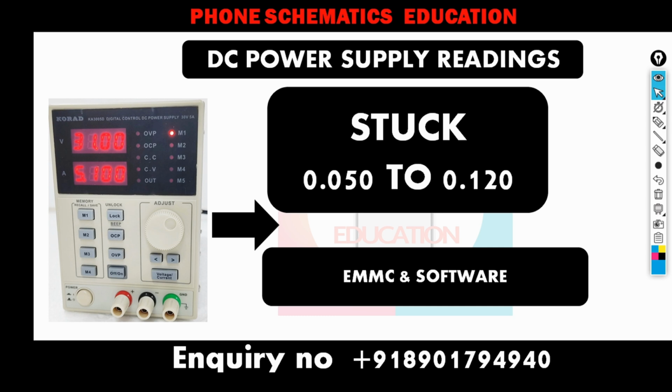Mostly EMMC. Also the software, your firmware. When the software is corrupt or the EMMC health is bad, or the EMMC requirements, the voltage requirements and other requirements, are not completed, your phone behaves like this because your power IC boots and your CPU responds. But when it goes up to the EMMC, then the CPU does not find the EMMC. The reading is stuck, or maybe there are software complications.